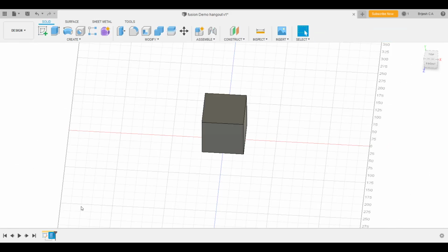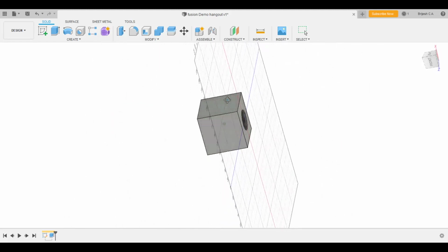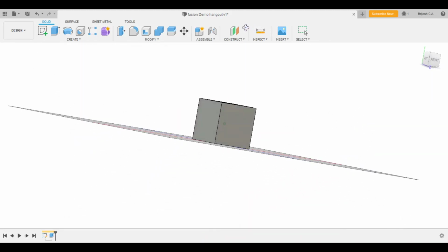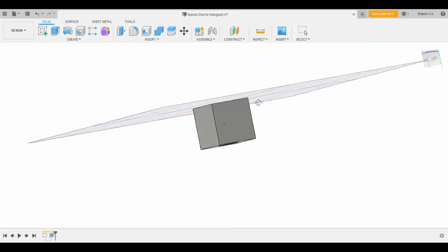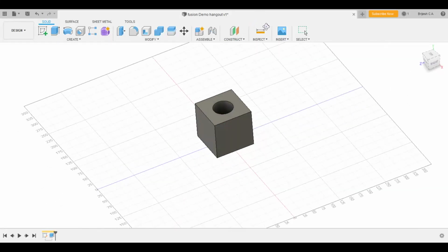finish sketch. Now when I click on extrude, I want to edit the feature. Here, instead of selecting the entire thing, what I do is I select only the outer surface for 100 mm and say okay. Now this is one option I have. I created this.